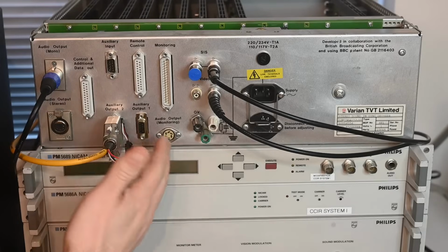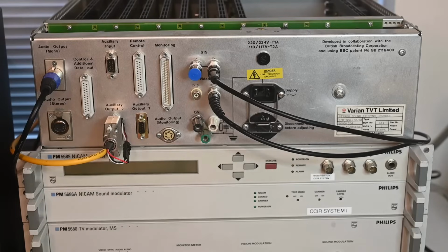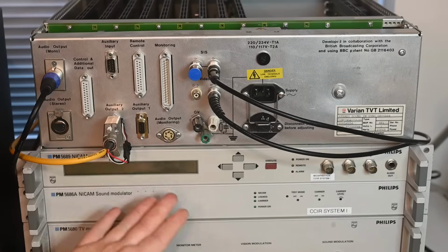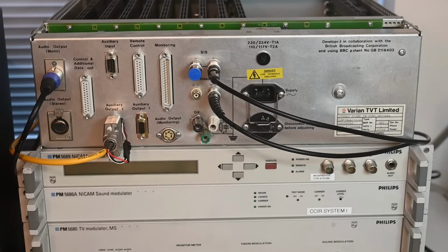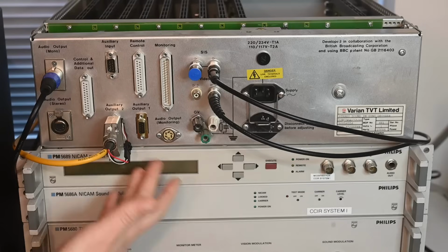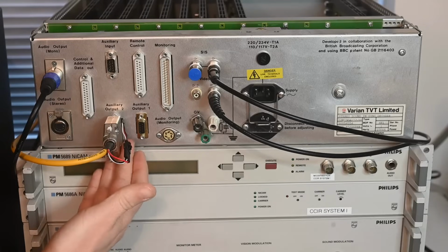The serial data output on this SIS decoder is this funky proprietary interface. Now, let's suppose the year is 1995 and TVT has long since been shut down, and whatever hardware was originally attached to this is no longer available, and you want to set up a new transmitter. You have the SIS decoder, but you don't have whatever equipment plugged into this. Well, then you've got a slight problem. And this interface here is a line driver which converts TTL to this 75 ohm bipolar type interface, inverts the polarity and what have you.